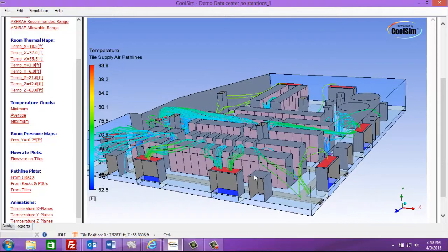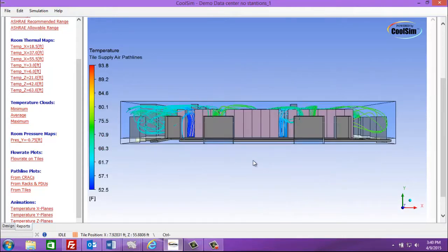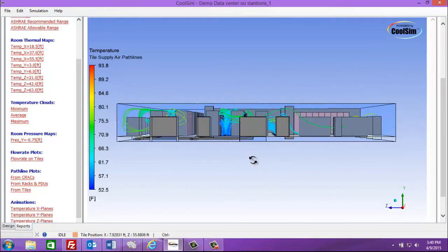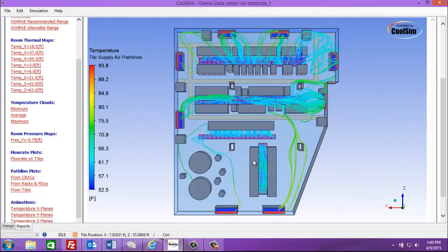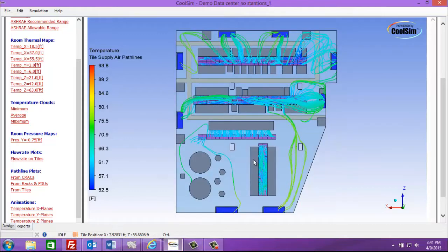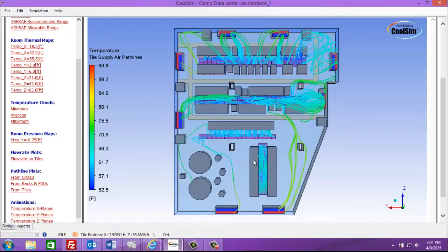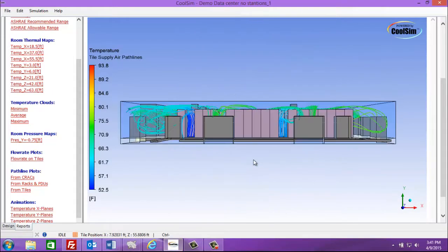First of all, remember that it does support keystrokes. So I'm currently looking at path lines. If I wanted to align it, I can align it along the z-axis or the x-axis or the y-axis. I can also turn on and off perspective. Those were x, y, z keystrokes respectively, and that shuts off perspective, so you can look at it straight on. Now let's take a look at it from a Z point of view, and let me show you a couple other things. Let me go X.